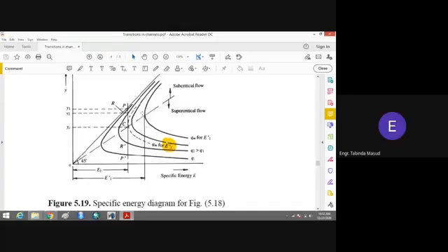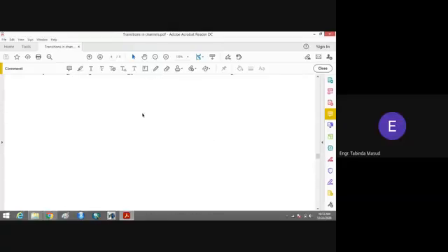Then what will happen? Again, we will have the same situation. In case of the hump, we say that when the height of the hump goes beyond the critical hump height, then there is damming action, that is, the level of water at the upstream side increases. Similarly, in case of the contracted channel, if we further provide the contraction beyond the minimum value, then there will be a damming action at the upstream side of the channel.